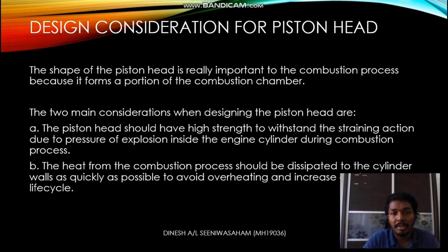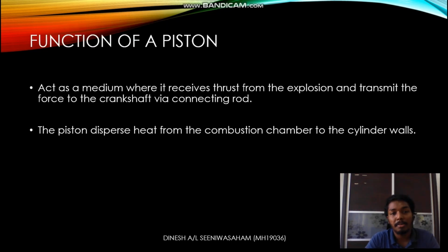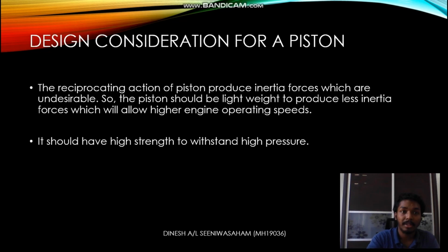Design consideration for piston head. The shape of the piston head is really important to the combustion process because it forms a portion of the combustion chamber. There are some considerations when designing the piston head, which is that the piston head should have high strength to withstand the straining action due to pressure of explosion inside the engine cylinder during the combustion process. Next is the piston. The piston actually acts as a medium where it receives a thrust from the explosion and transmits the force or energy to the crankshaft via the connecting rod.